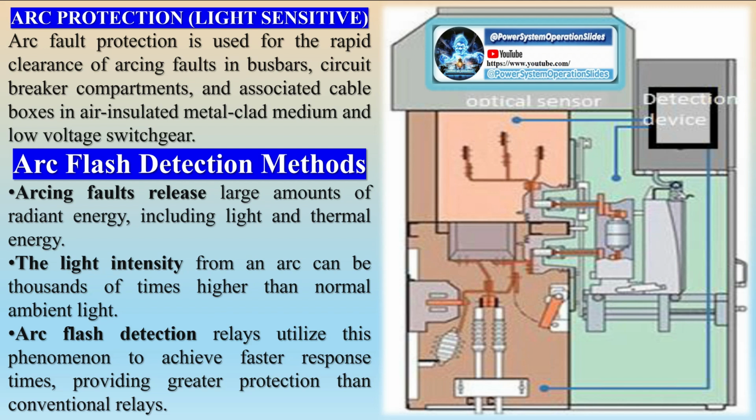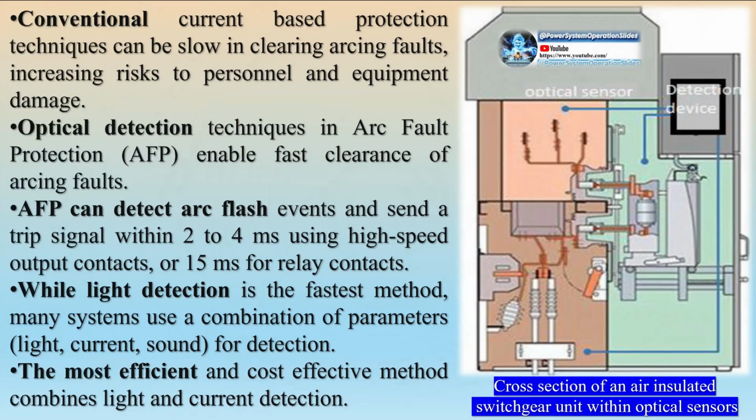Main requirements: security, a low probability of unnecessary protection operation for through faults or out-of-zone faults. Dependability, a low probability of failure to operate for a fault on the bus, an in-zone fault. High-speed operation to limit equipment damage and preserve system transient stability. Sensitivity, the ability to detect and clear high-resistance faults. Selectivity, the ability to isolate only the faulty bus section.